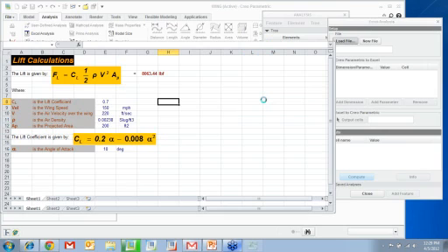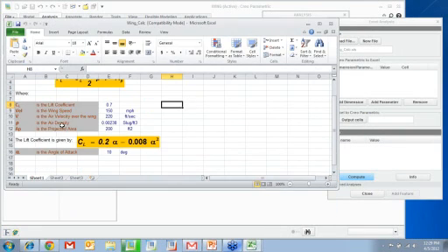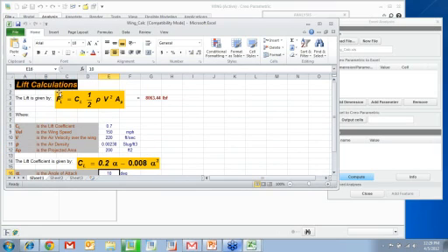So you can see there's a lift coefficient, there's a wing speed, there's an air velocity, there is an air density, there's a projected area which we will be sending to this Excel file. There'll be an angle of attack which we will be sending to the Excel file. And this uses this particular calculation and tells me how much the lift force is.